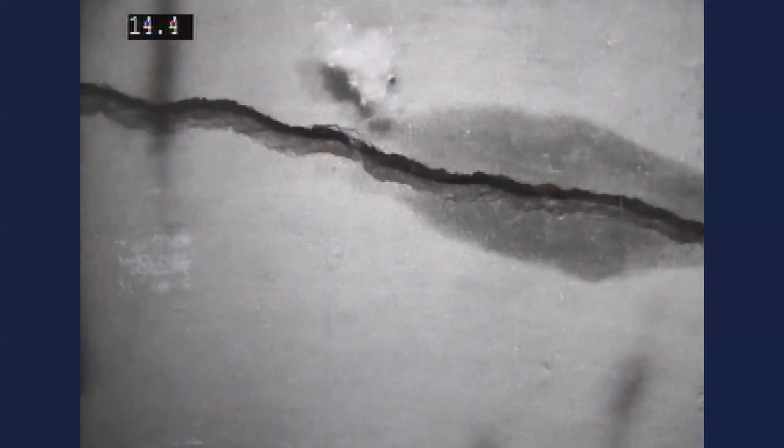This is one where you could observe it over a 6-month period, and during the stormy season when you have water in the crack, you could see whether it's going to heal or not. You could observe it and see what's going to happen, and then go from there. And if you do need to, this would be a good candidate for an injection grout along the width of that joint, just to seal it up and make sure that the water isn't leaking, it's not causing any damage, and it's not rusting out the steel in there. So that's a viable option for this one.